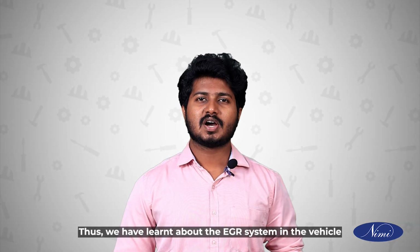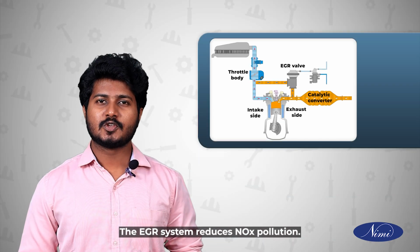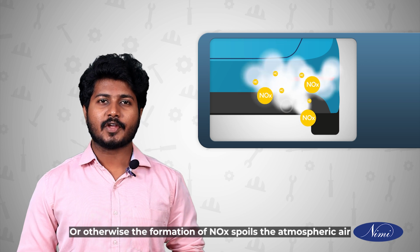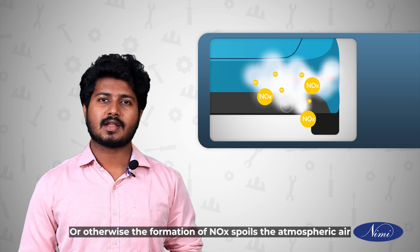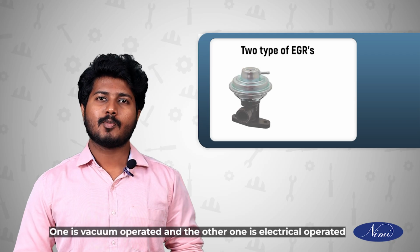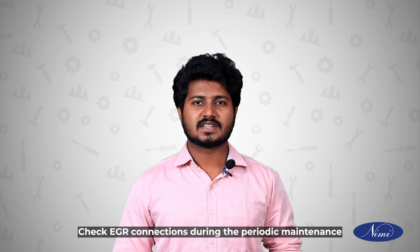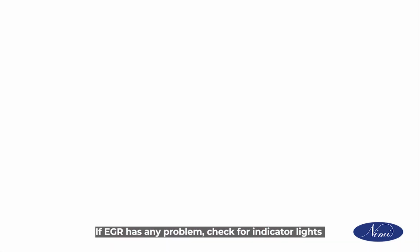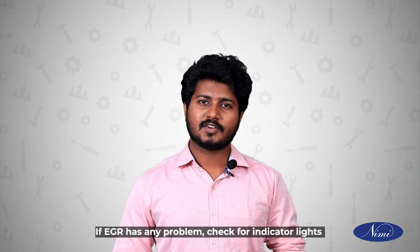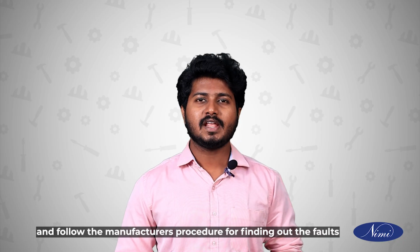Thus, we have learned about the EGR system in the vehicle. The EGR system reduces NOx pollution, otherwise the formation of NOx spoils the atmospheric air and leads to knocking. Two types of EGRs are available. One is vacuum operated and the other one is electrically operated. Check EGR connections during periodic maintenance. If EGR has any problem, check for indicator lights and follow the manufacturer's procedure for finding out the faults.